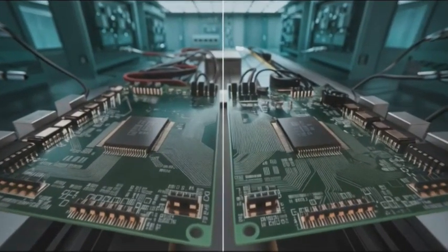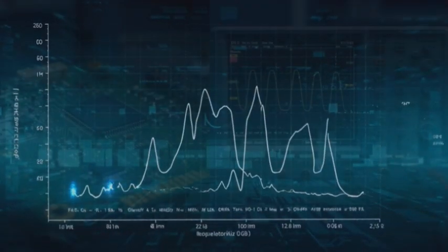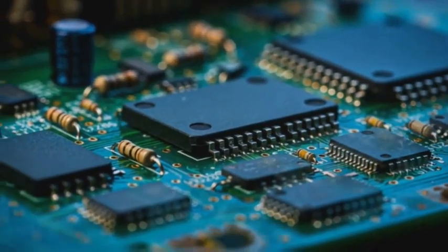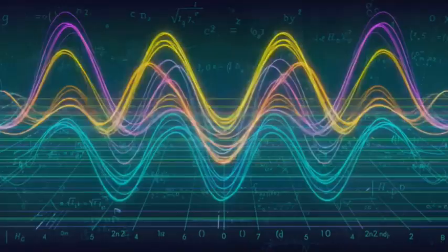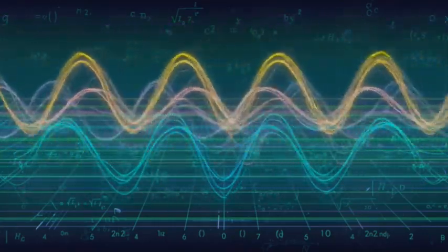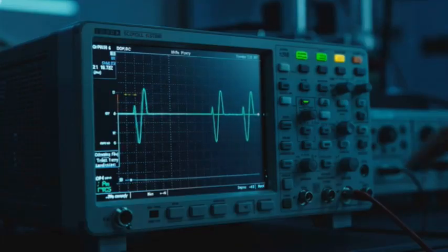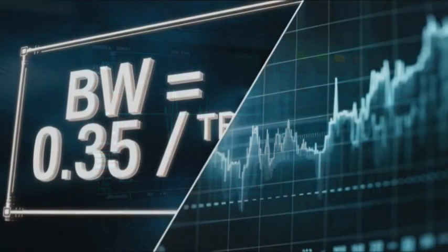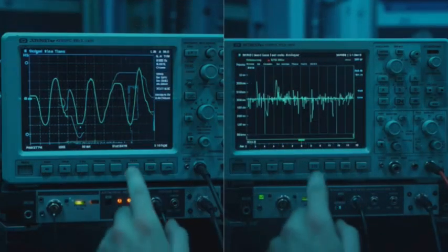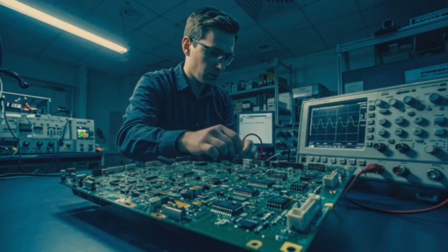impacted by RF interference. Digital signals like a 10 megahertz square wave actually contain frequency components extending to gigahertz. The Fourier theorem explains this through sinusoidal harmonics, decreasing rapidly at higher frequencies. The bandwidth limit, determined by rise time, marks where these harmonics become negligible. For instance, a 1 nanosecond rise time has a bandwidth limit at 318 megahertz.